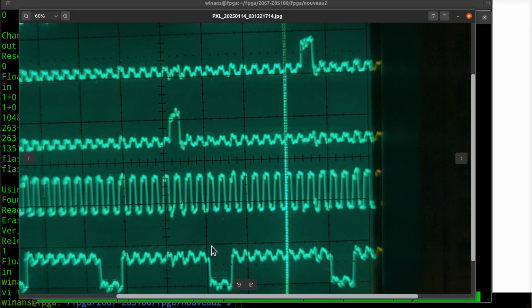What do we got here? M1 goes true, and there's T1, T2, T3 to read its opcode. And this is an out instruction, so it has to read the immediate operand, 1, 2, 3 cycles for that. There's an extra T state right here that it uses internally as part of the instruction. So far that is 7 T states. And then we've got the 4 T states over here to do the I/O cycle.